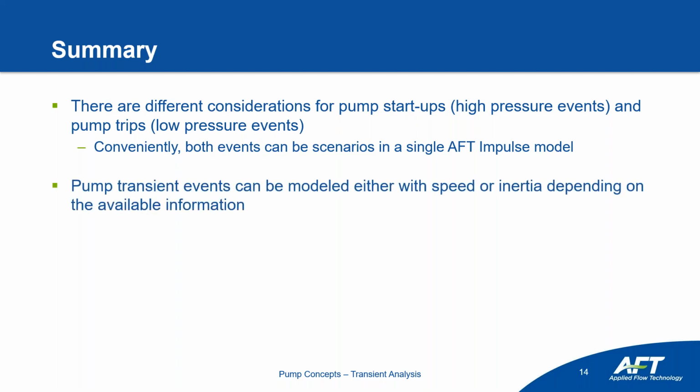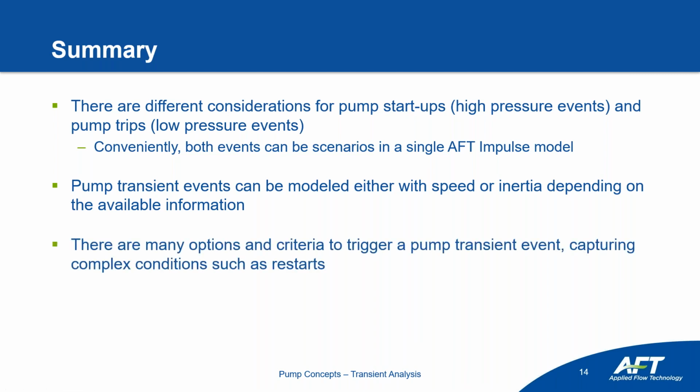Pump transient events can be modeled either as speed or inertia. That all depends on the information that you have available. And it can also depend on if you're doing a controlled startup or an uncontrolled startup. There are plenty of options and criteria to trigger a pump transient event.